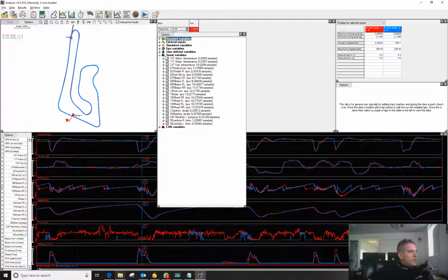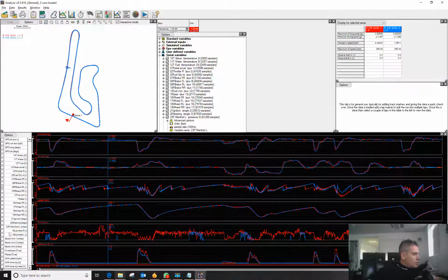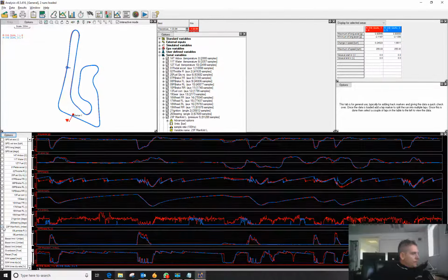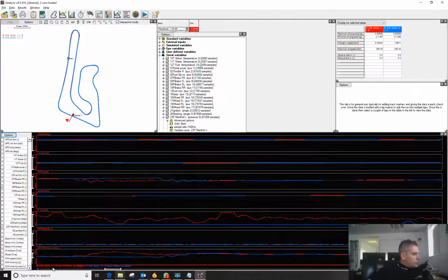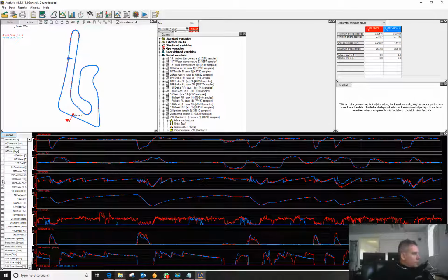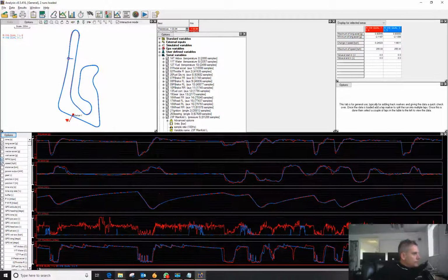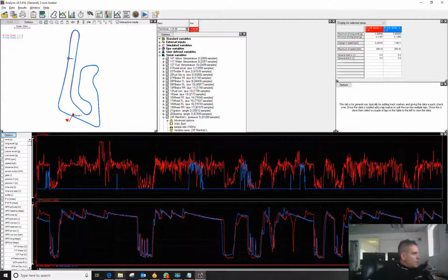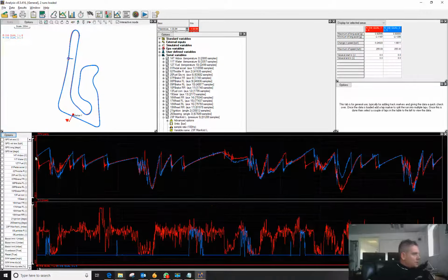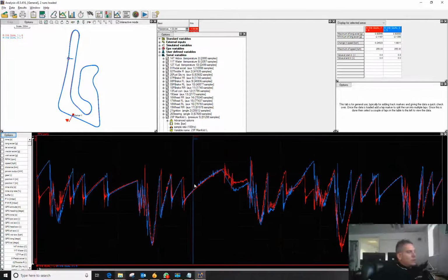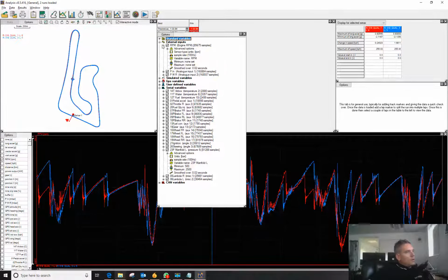So in here, if we select a channel like boost pressure, I'll just switch some of these channels off. In fact, RPM, I use RPM, it's better. So the RPM data here, RPM is stored under external inputs.